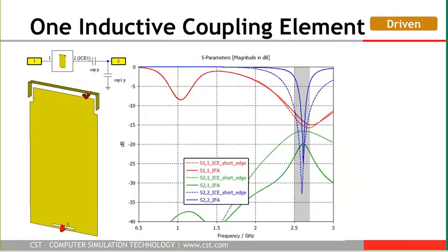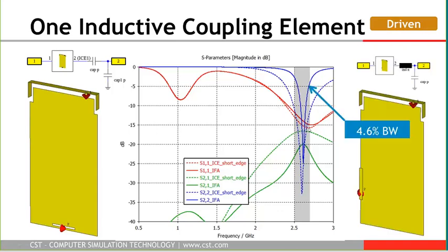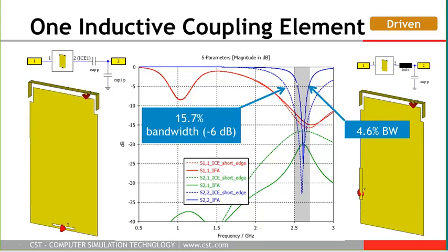So we have done that. We have placed the slot to the maximum current of the diversity mode. We have again attached the matching circuit, optimized the values of the matching circuit, and in the middle you can see the result. The solid line denotes the standard workflow with inverted F antenna, which I've shown you before, and the dashed lines denotes the characteristic mode approach.